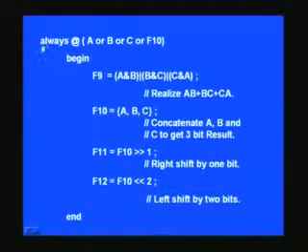And you would notice there is one always statement here. And what all it means is, whenever inputs such as A, B, C and F10, any of these inputs changes, only then this will become active, otherwise not. Right? These instructions will be, so to say, executed only when any of these inputs change from the previous value. Right? And if you have multiple statements like this, you need to put a begin and end, indicating the whole thing is blocked as such. In one block, you can put as many instructions as you want, really. And another thing is, when the statement is complete, you just end up with a semicolon there.